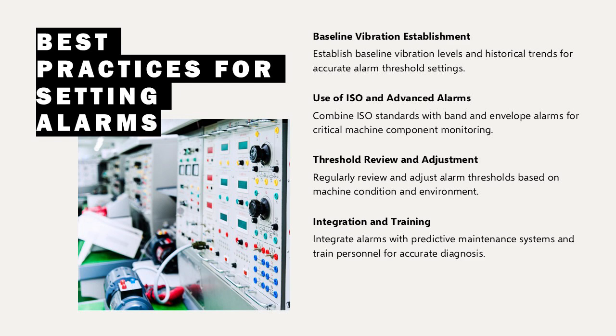Regularly review and adjust thresholds based on machine condition and operating environment. Implement automated alerts and integrate alarms into predictive maintenance systems for timely interventions. Training personnel on interpreting alarm data is equally important to ensure accurate diagnosis and corrective actions.